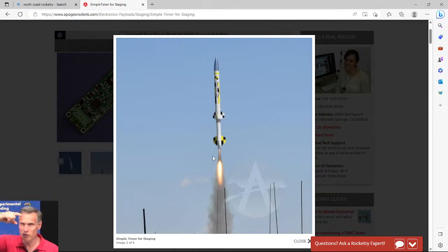And when the altimeter sees that the pressure is increasing, it says, "I've reached apogee," and it deploys the parachute. But barosensors can be tricked by a gust of wind, because if the rocket's sitting on the pad and a gust of wind comes along, that gust of wind acts like the pressure is increasing. So the altimeter, when the wind comes along, thinks that the rocket has already reached its apogee and is starting to come down.